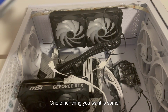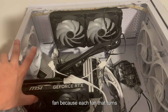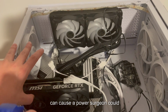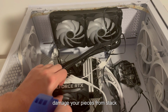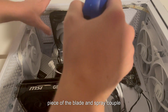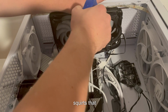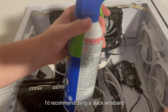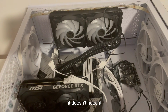One other thing you want is some compressed air. You're just going to hold each fan, because each fan that turns can cause a power surge and could damage your pieces from static charge. So I'm just going to hold the piece of the blade and spray. A couple of squirts. If you have one, I recommend using a static wristband. If you're just spraying like this, it doesn't need it.